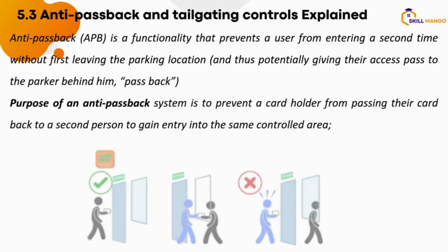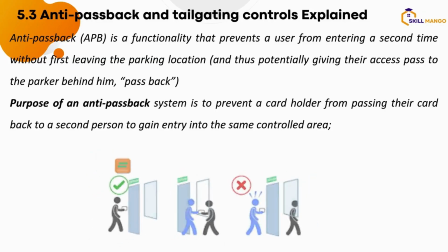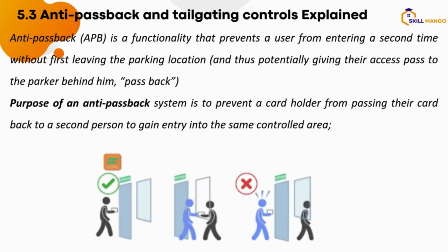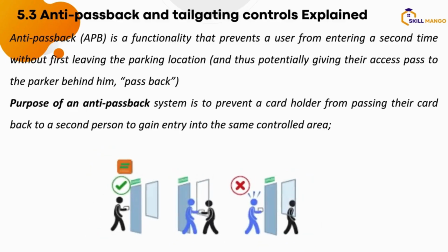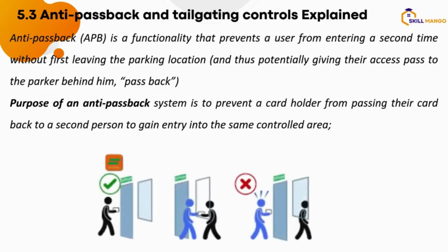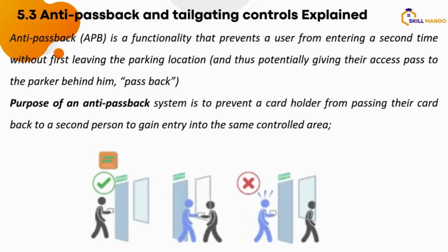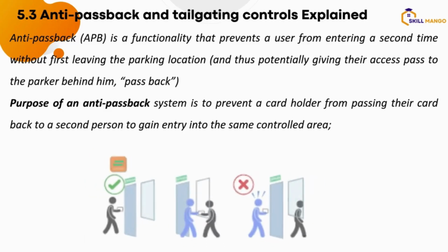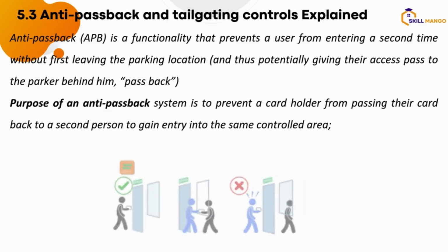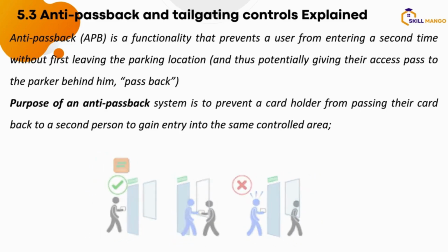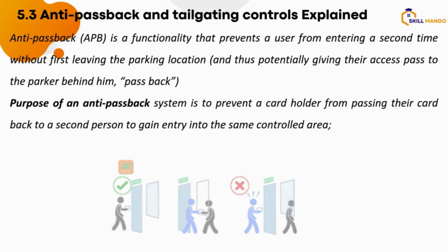Do you understand? So it's a very basic setup or configuration. Reader in, reader out, to deploy the anti-passback technology or solution. All right. So your reader in, reader out, then exit button, mag lock at the top of the door, then your power supply, and you do your connection, which I'm going to do practically for you to understand. You follow your color coding, cables, and stuff like that.